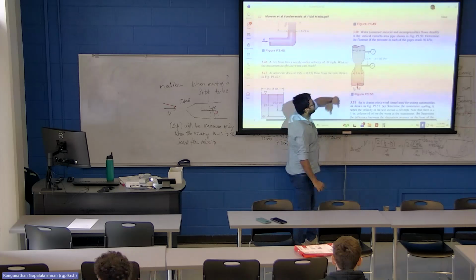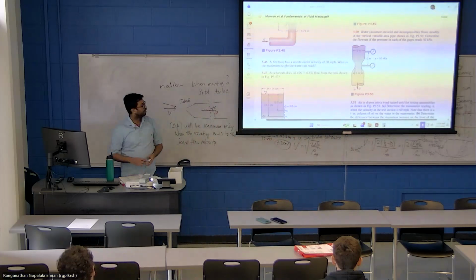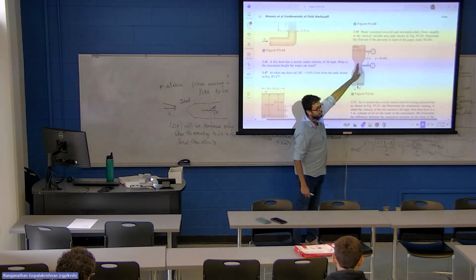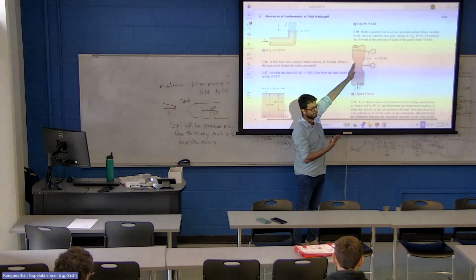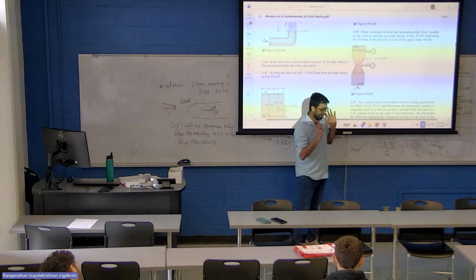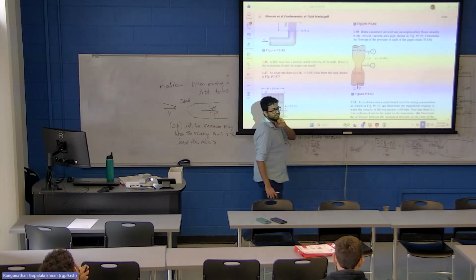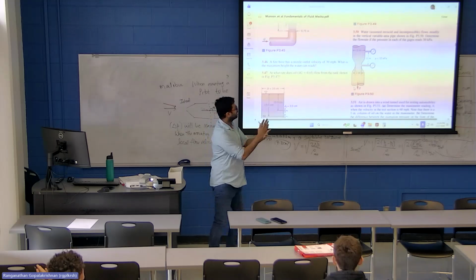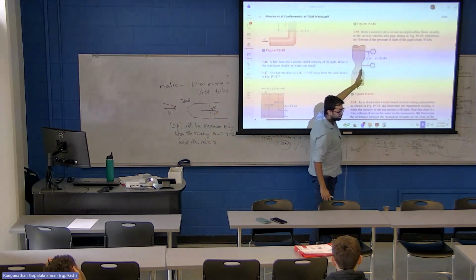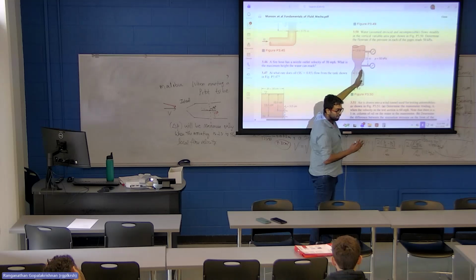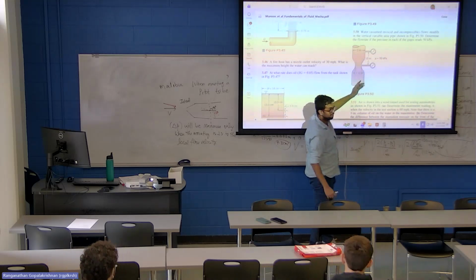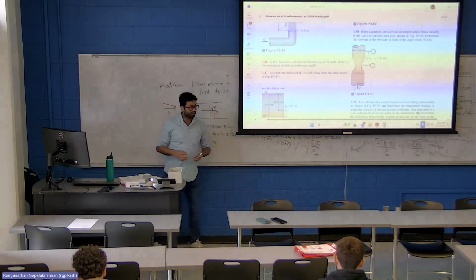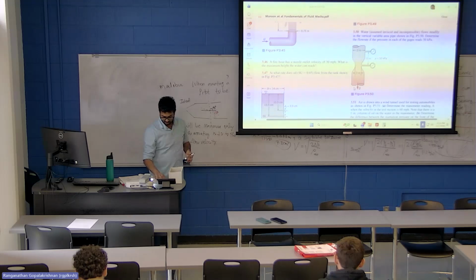Okay, the next step is to identify the streamline which doesn't bend or have any curvature, one that is unaffected by the cross section change. That is the one axially at the center. The central streamline, passing through the axis of this tube, will not bend or change. It will just go through straight. So I'm going to turn this off and draw.